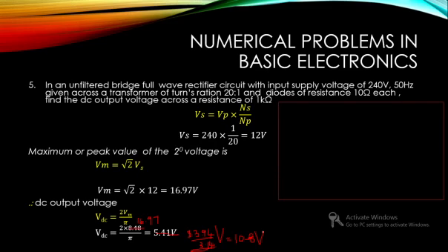So the same question can be applied to a half wave or full wave, or a bridge full wave or center tap full wave. So based on your understanding, the answers will be different. Okay. So here also you can calculate what is the load current, which is corresponding voltage, that is VDC. IDC is given by VDC divided by RL.